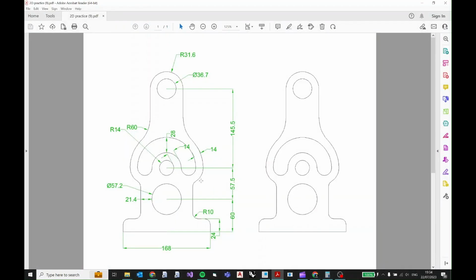The next thing I'm going to do is make this circular arc, and you can notice that this circular arc is a part of one circle. So I'm going to make a circle centered on the origin, and you can notice that this circular arc doesn't have a radial dimension or a diameter shown on it explicitly. What I mean by explicitly is that it's not shown on the drawing, but you are still able to calculate it based on the other dimensions that are given.